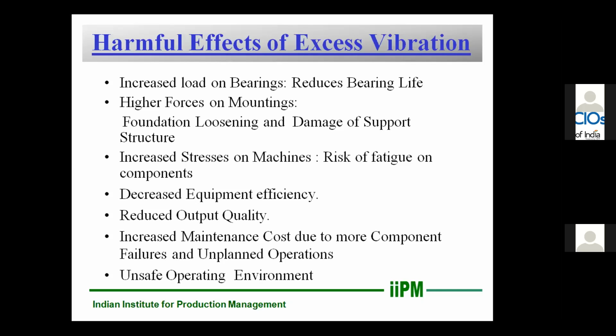Then comes the higher force on mounting. If forces are high, then your foundation bolts will become loose, your structure will crack. What happens when the machine runs? Things become loose: pipes, supports, flanges, bearing, foundation bolts.